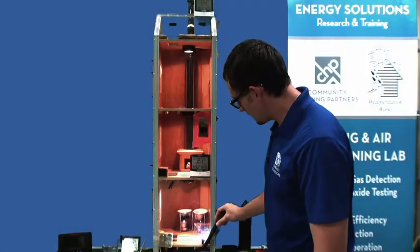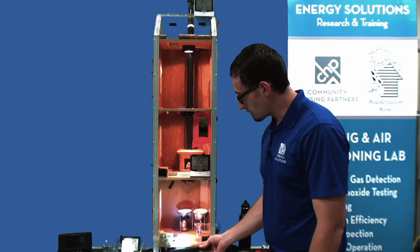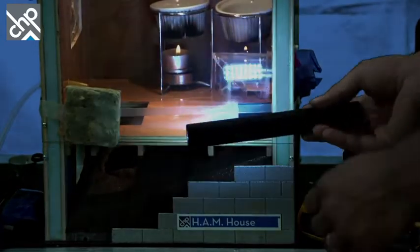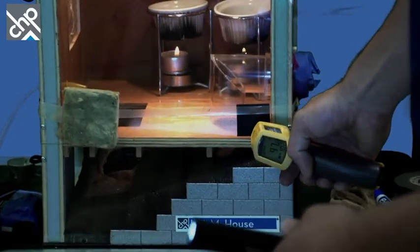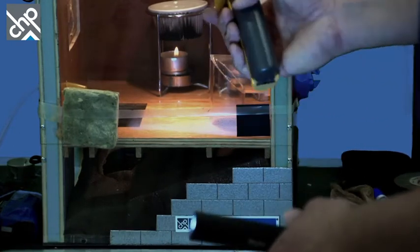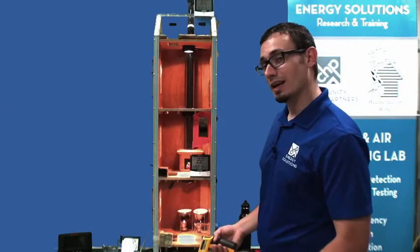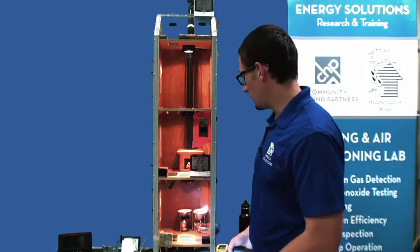I can start seeing the moisture filling in on the edges here, starting to run across the bottom. Going to get really foggy really quick here. So again, let's just do a quick check. Surface temperature down here at the bottom is about 93 degrees. We just surpassed the dew point of 94 degrees. So remember, anything at or below the dew point is going to have condensation present on that surface.